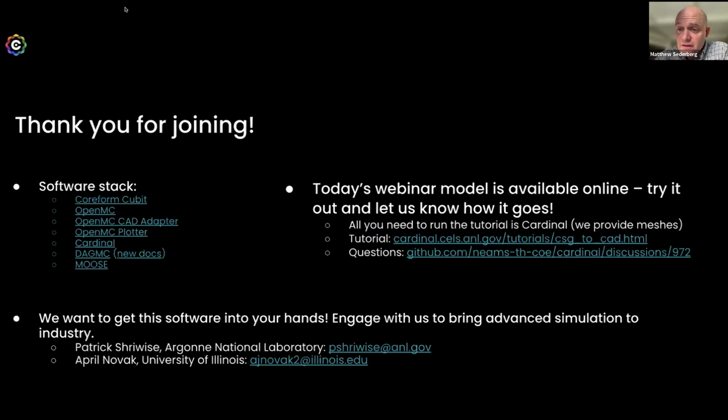Ibrahim asks, how sensitive is K-effective to the fidelity of the mesh? Yeah, this is a really good question, and something we've looked at extensively in DAGMC. This is where the faceting approximation, or what is also referred to as the faceting tolerance, comes into play. It's really important because that essentially defines the difference in your volume between the analytic part and the meshed part.